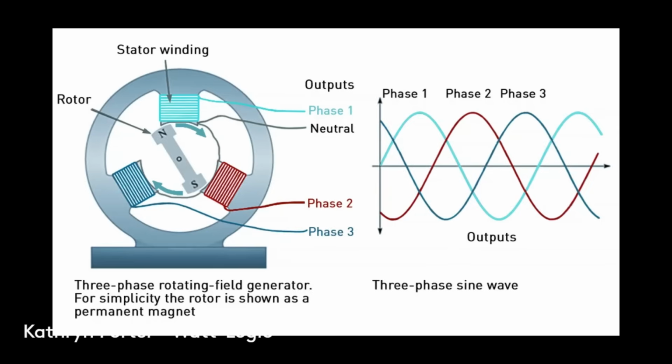As well as having inertia, which we've discussed in a previous video, so that is these big heavy turbines resist changes to their speed of rotation, synchronous generators also control reactive power by adjusting the field in the electromagnets that create the electricity in the first place. When I said that you have one magnet rotating inside the magnetic field of another magnet, those two magnets are electromagnets. So effectively wires wrapped around some metal, and the current is passed through those wires, and by varying the amount of current going through those wires, you change the strength of the magnetic field, and that changes the properties of the alternating current, the voltage and the current that gets then induced by that process.